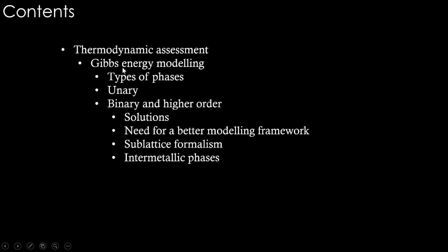These are going to be the contents. We'll focus on how Gibbs energy is modeled based on types of phases, and then we'll focus first on unary systems and then binary and higher order, where we will first see solutions. This is something that we have seen in the introduction to computational thermodynamics just before the hands-on sessions. And today we will focus more on the need for a better modeling framework, and we will look at sublattice formalism, and using that how intermetallic phases and even solutions again can be modeled in this framework rather than the method that we have seen before.